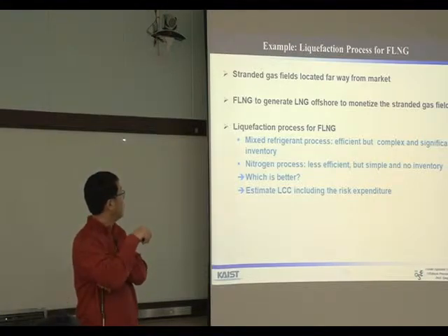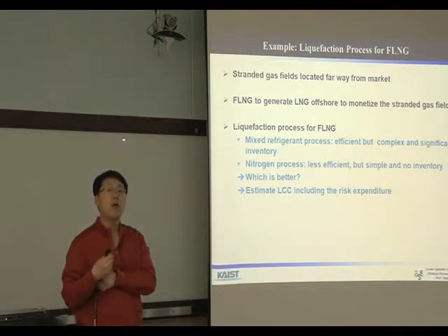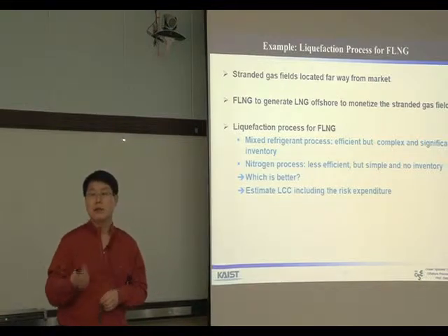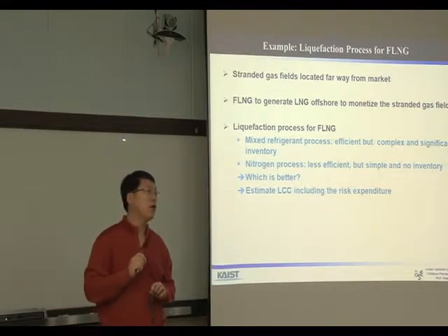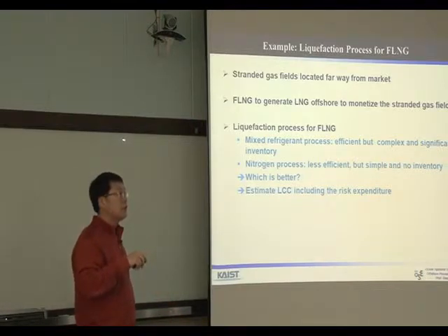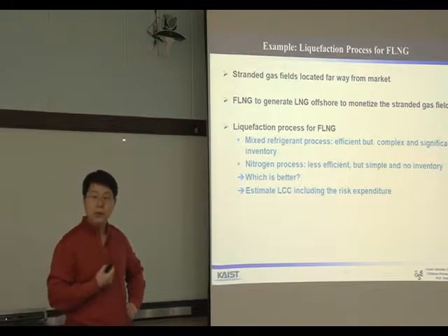Another option is the nitrogen process. The nitrogen process is less efficient. It consumes more energy than the former, but it is simple and has no inventory. The nitrogen does not cause fire and explosion. So the mixed refrigerant process is efficient, but less reliable and less safe. The nitrogen process is less efficient, but more reliable and more safe. So which is better?